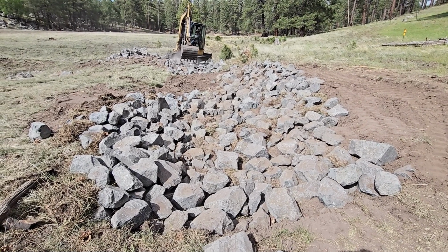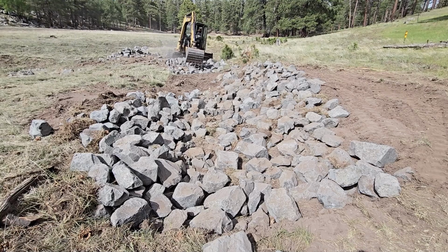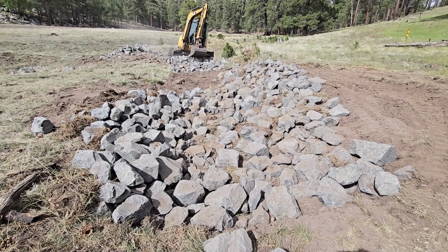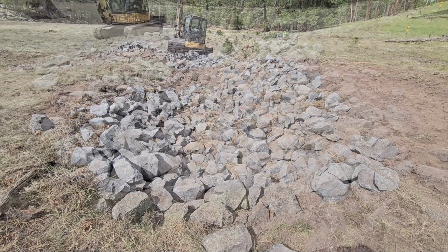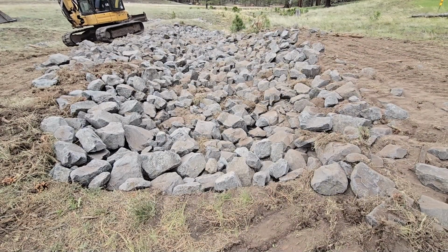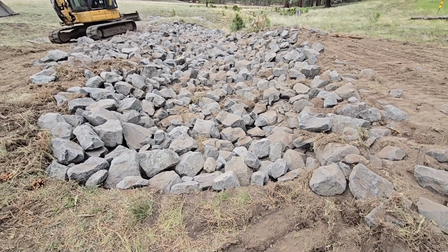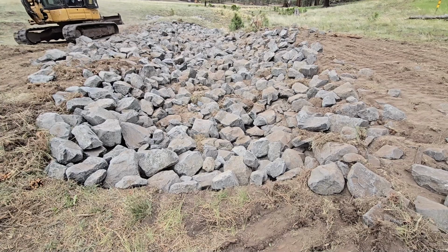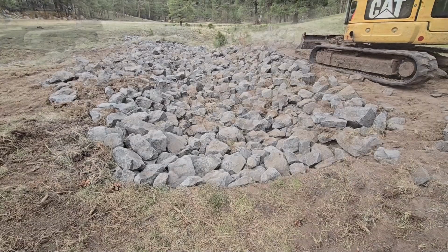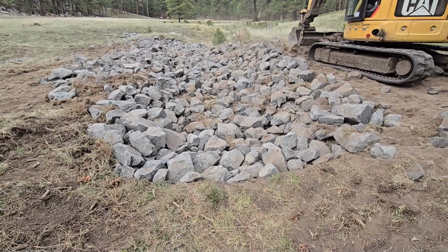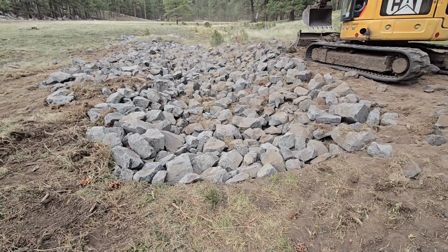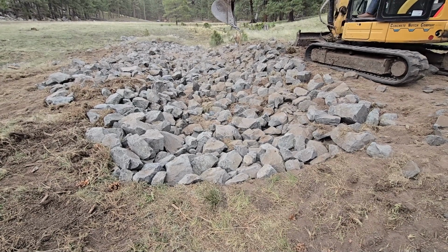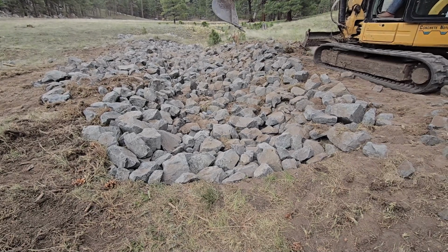He works to maintain a shallow valley on a gradual slope with a wide floodplain so that the water will spread out and flow over the rock in a sheet-like pattern. He uses the weight of the machine to push the rock into the ground. This is difficult to accomplish because the rocks are large and the ground is compacted. Don works to taper the outer edge of the floodplain and to fit the rocks tightly together. He also begins covering the outer edge of the rocks with soil to form gradual stream banks.